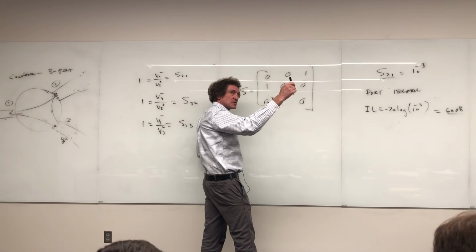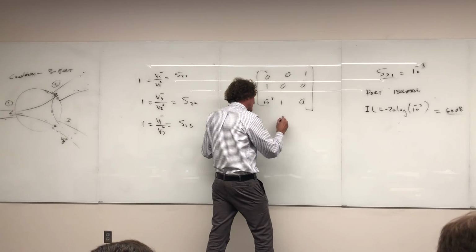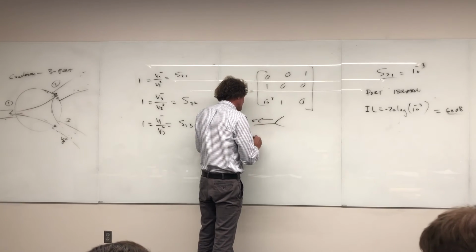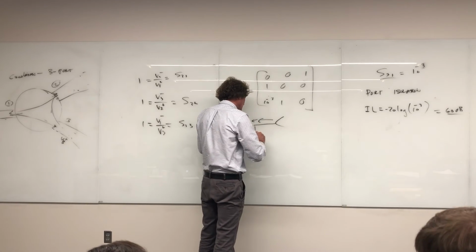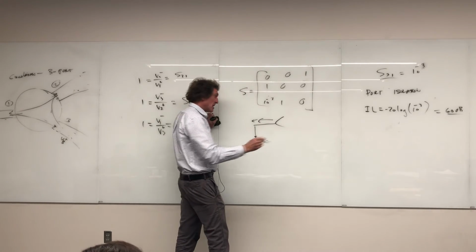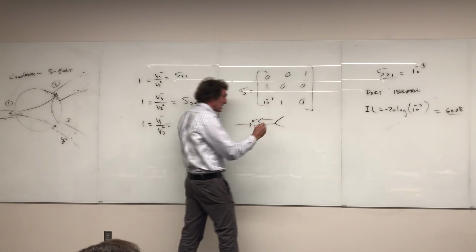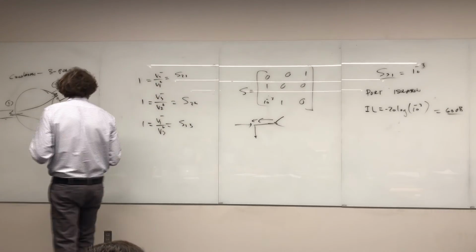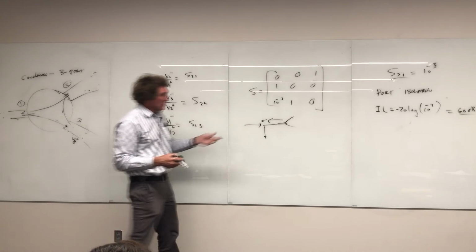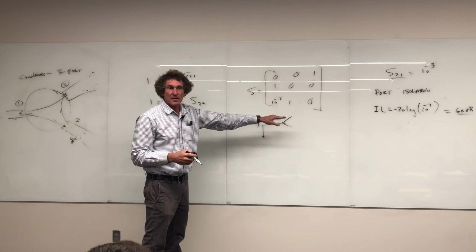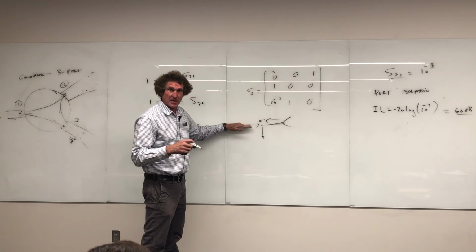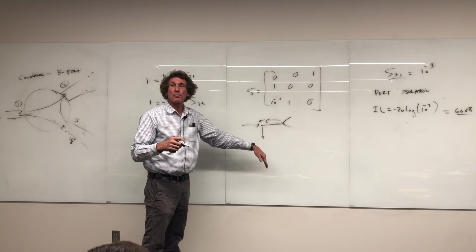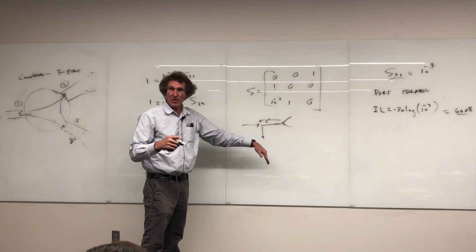They're mainly used if you're having things where you want signals separated. Suppose I've got an antenna here, right? And I want all the signal coming this way that's being received to go to some kind of digital processing thing, but I want all the signal coming this way to actually go to the actual device. Do you follow me on this, class? Well, with a circulator, you can do that fairly straightforward because now you would have the feed on that antenna, say coming out port 2, if it was being fed from port 1, and then everything coming back on that antenna, you'd shunt out port 3 for processing. Do you all follow me?